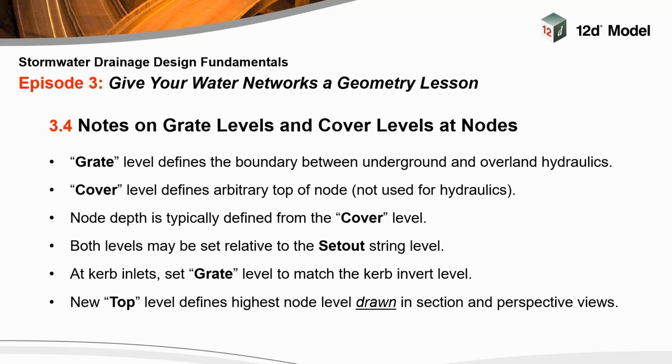And this is just a few comments on grate levels and cover levels. I've mentioned them a few times already, but I really want to tell you exactly what they are. And I've used the words grate and cover in quotes here because I kind of regret ever calling it a grate level. It was my fault. There doesn't have to be a grate at this node. There might be or there might not be. So every node, though, has a grate level, and for hydraulic purposes, it is probably the most important level, and it shouldn't be overlooked for hydraulic purposes.